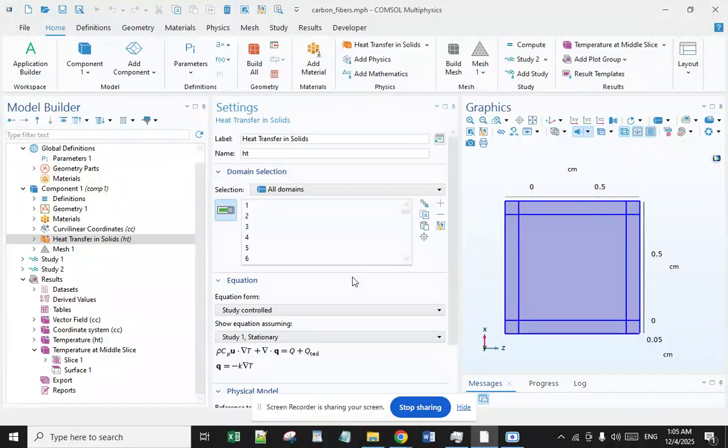Thermal study of carbon fiber reinforced polymer composites using multi-scale modeling. The layer fibers of carbon fiber reinforced polymer composites exhibit low thermal conductivity, or TC, throughout their thickness due to the poor TC of the polymeric resin.